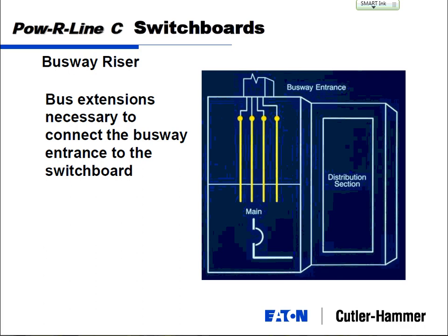The same thing applies when you're going vertically. And when you're going vertically, busway actually has the option of being able to tap off every floor. If you want to tap off every floor with a circuit breaker, you can put a circuit breaker on every floor, and it's a great distribution method. But I won't get ahead of your design.